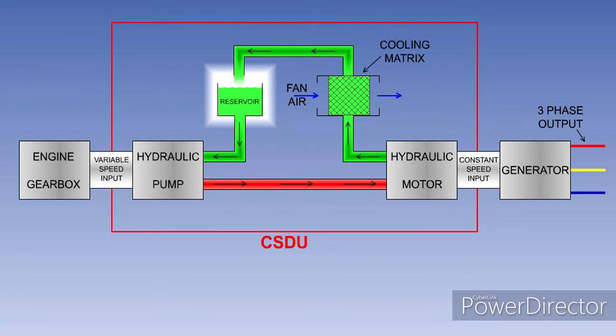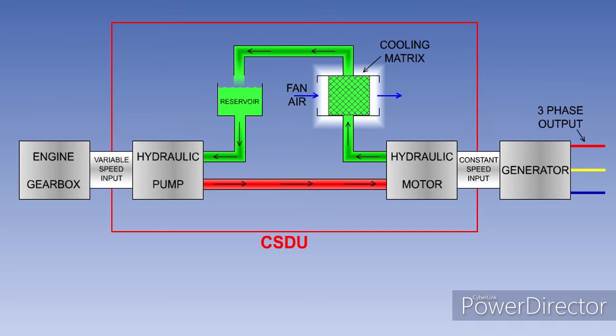The oil, as well as being the fluid through which the mechanism operates, is also used for lubrication and cooling. It is contained within its own reservoir, entirely separate from the engine oil system. The oil circulates through an oil cooler, which uses ram air, or, on a bypass engine, fan air, as its cooling medium.